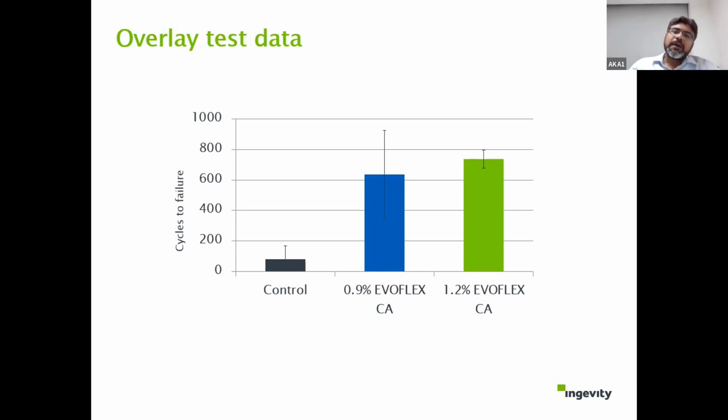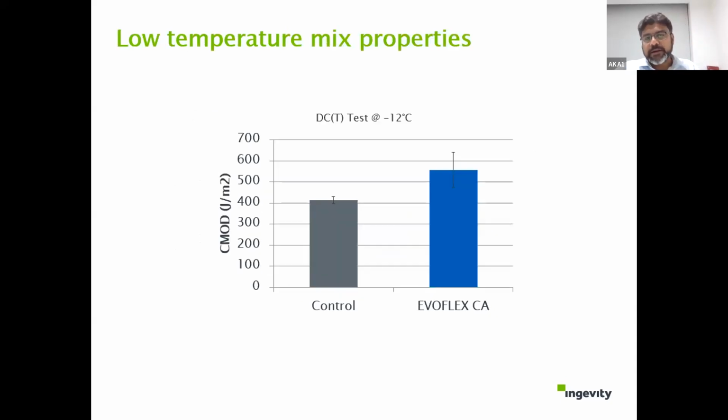That is why, again, I don't want to get into the balanced mix design or the IDEAL-CT test. I think many people have already covered it. Our objective is to say that you get rutting values that may be a little less than what you compare to the typical RAP mix. But again, it may crack at low temperatures. So we are trying to find a range where you pass your fatigue failure as well as the rutting criteria. This is again based on the DC test.